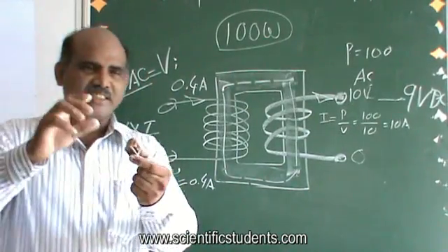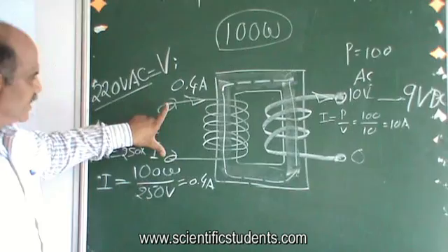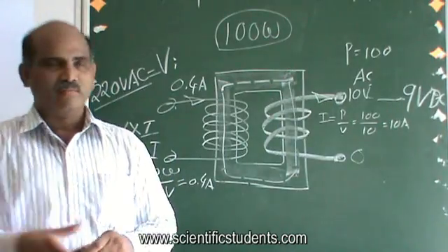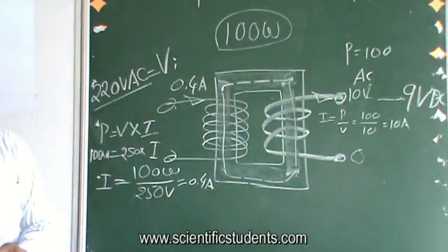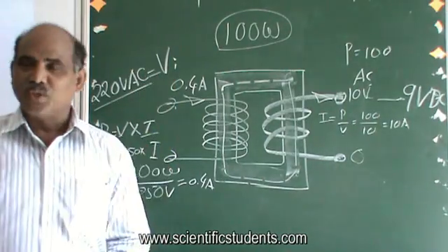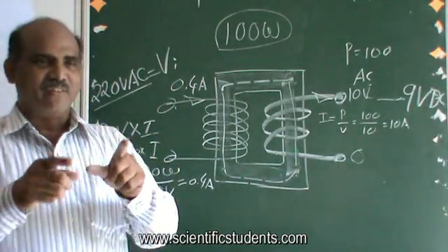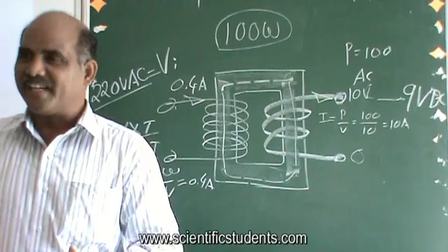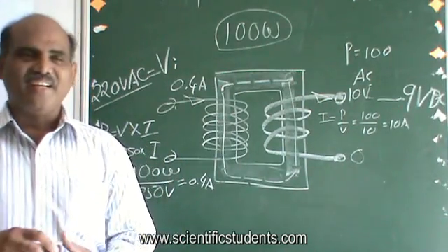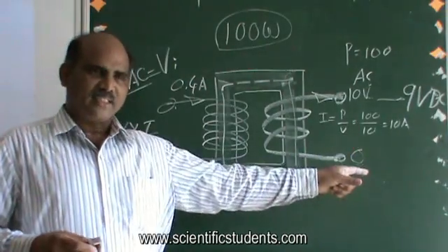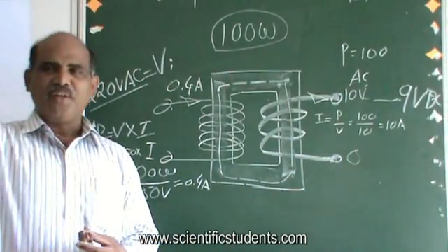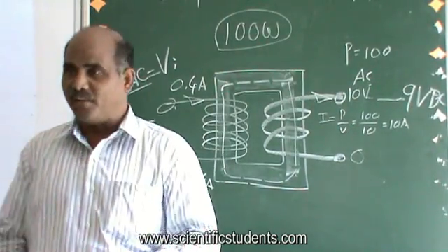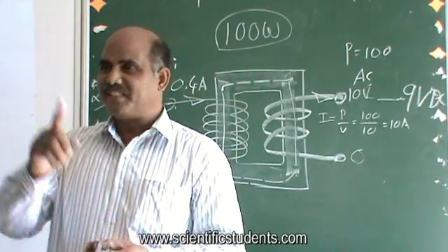So you just measure the resistance of these two windings. You measure the resistance of this coil and also of this coil. Which one will be more? This one is more. So whichever winding has the higher resistance, that is the primary winding, to which you connect 220 volts. You understand? And the one with less resistance is going to be the secondary, from where you take low voltage, high current. My dear friends, this is the way you can understand which is primary and which is secondary.